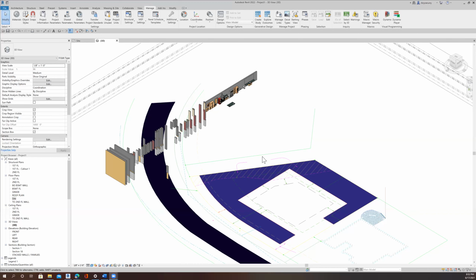So if I had 12, 15, 18, and 21-inch cabinet widths, and I needed a 24-inch cabinet width, I modified that family to have a 24-inch width. Now I have that as an option. I select it in my properties when I'm looking for a different cabinet. I don't have to go in and change the constraints of it to make it 24 inches.